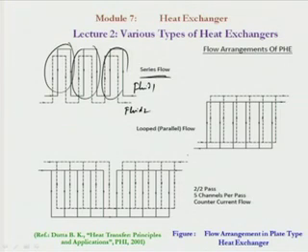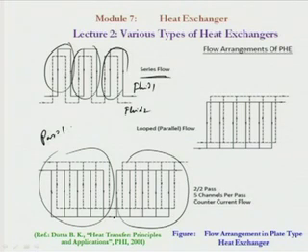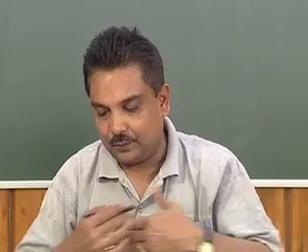There are two different arrangements, as I told you, that in plate type heat exchanger the arrangement can be of different types, and this is a typical, little bit more complicated arrangement. We can see that this is 2 pass, 5 channels per pass, counter flow arrangement. This is 5 channels, we can see 1 2 3 4 5 channels, here also 1 2 3 4 5. So 5 channels per pass. This is one pass, this is another pass. Therefore it is called 2 pass arrangement. First it is coming like this, and then after merging here, it is again distributed. Then this is the first pass, pass 1, and this becomes pass 2, because it starts from here. So again it is an anti-parallel flow or counter flow that is happening,